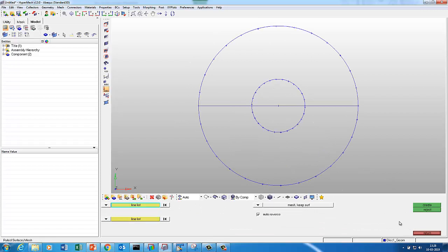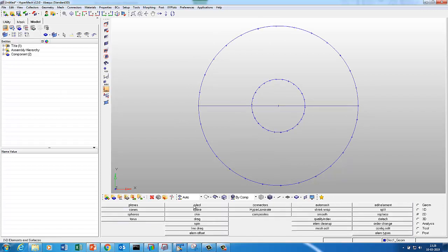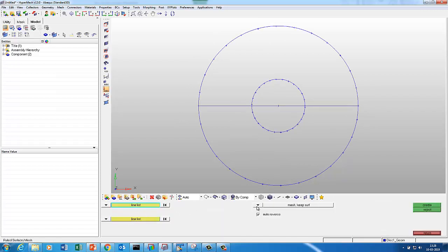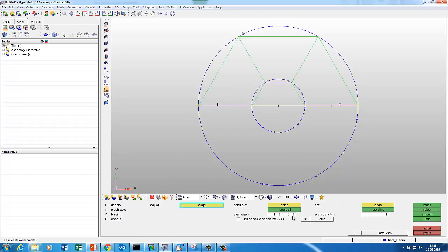So I'll go to 2D rule line list, and I say without surface. Why without surface? Because I want to have a good quality structural mesh. So I'm just going to choose point 125. I'll see how it looks like. So it will be very fine.